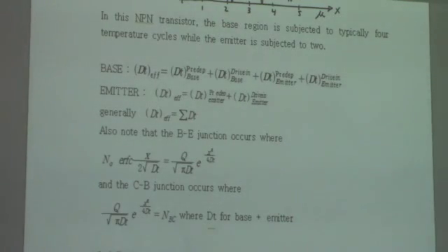to finalize the dopant profile, and for this case, for the base, the pre-deposition and drive-in for the base and emitter has to be exercised for this base dopant, so that the final diffusion length should be summation of all those diffusion processes. And for the emitters, we just have pre-deposition and drive-in if we have a drive-in.